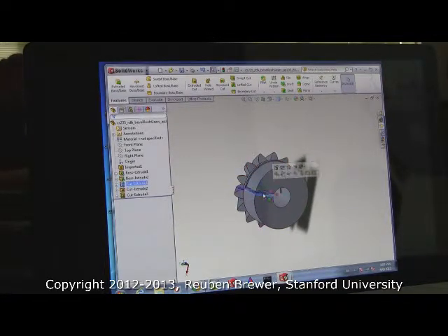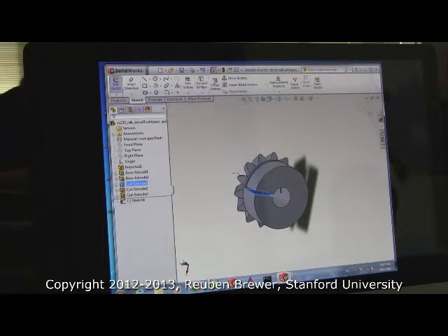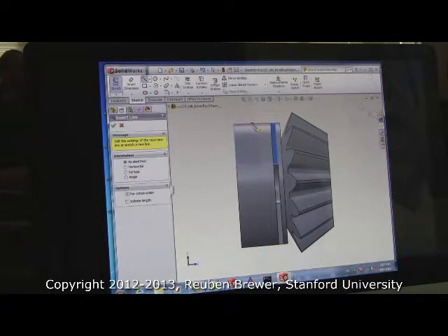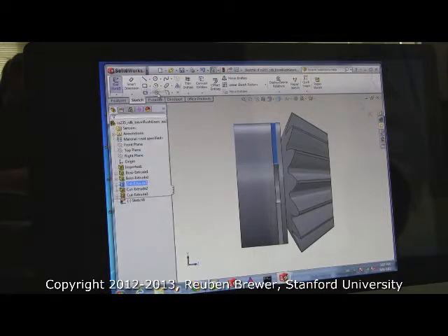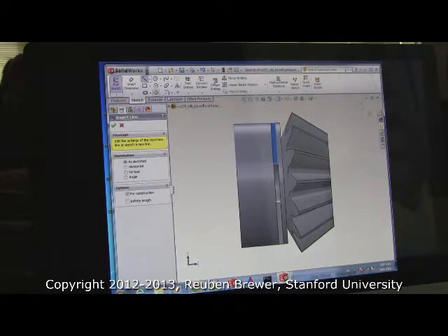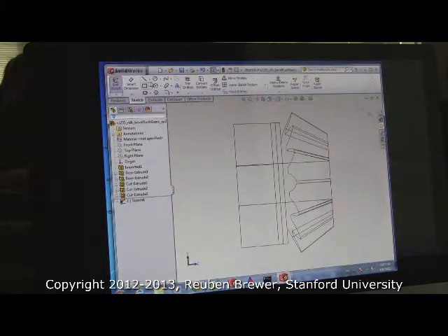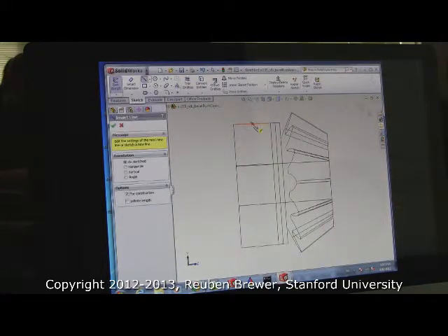Select this surface here and extrude cut and do the normal thing. Now I want you to switch to wireframe view so that we can see through. Actually, you know what? Don't do that. Keep it like this. Take a construction line. Wait, yeah, we do. Okay, go to wireframe view. Take a construction line and watch my screen for a sec.